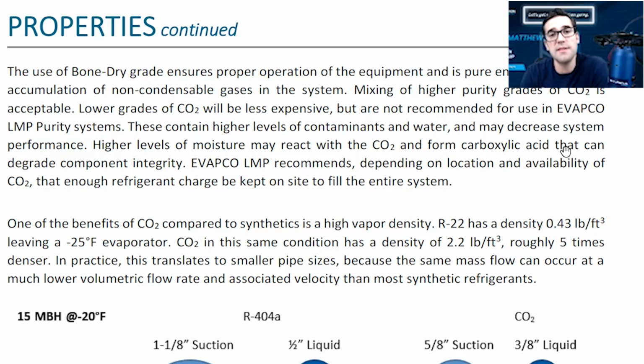And you should be taking samples once in a while, especially if it's a big process. If we're talking tens of thousands of pounds of CO2, because there are lots of systems out there that have that much CO2 in them, you've got to take some samples. And even in supermarket stores, when you have 2,000 or 3,000 pounds, a couple thousand pounds, you should at least take a sample when you're doing that oil sample and just have a look.